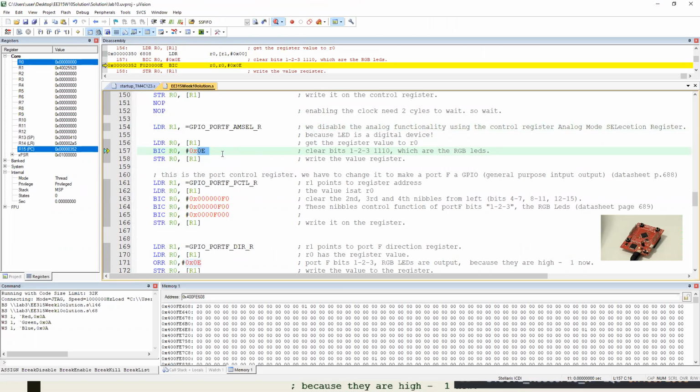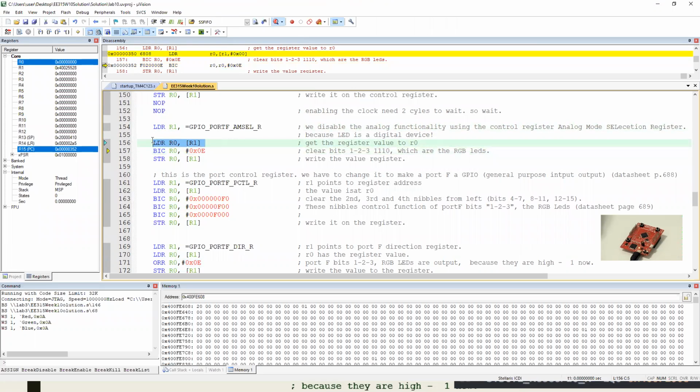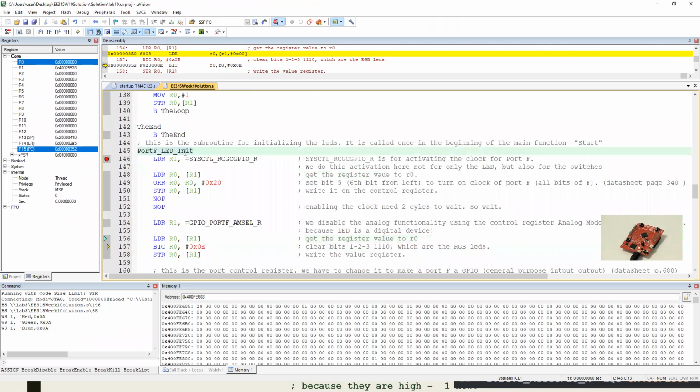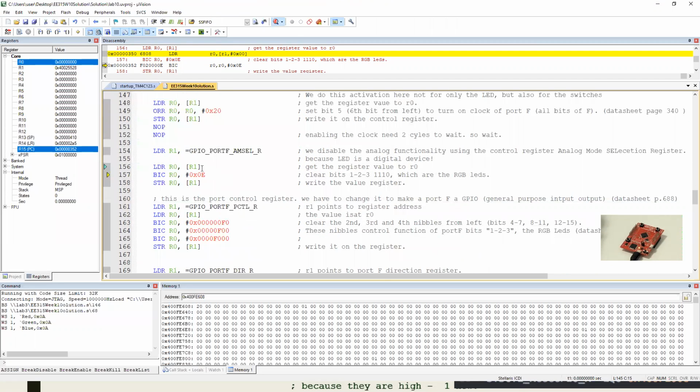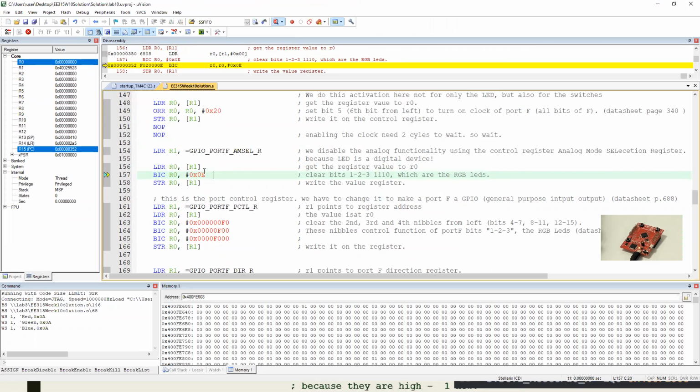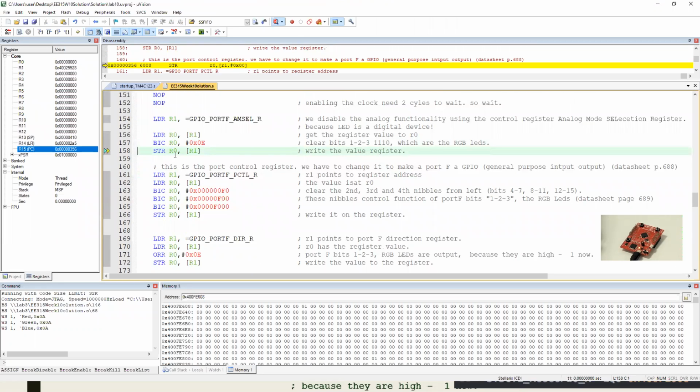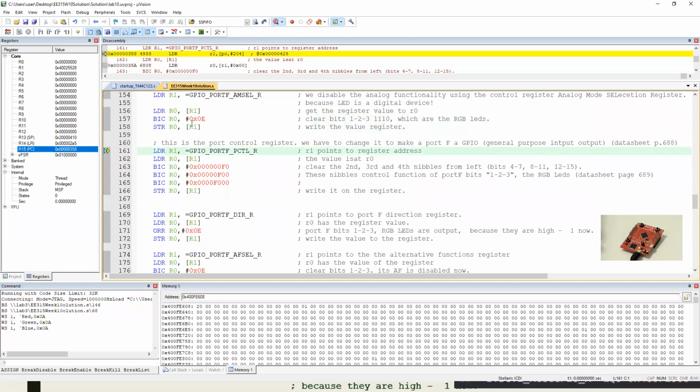So why am I doing this operation? Well, it is redundant, but I don't know if the initial value was this. When I reset it, it's 0, but maybe before calling this function, somebody else changed those registers and they were not 0. I don't know that. I know this because I'm debugging it. While you're running a big code, there is no guarantee that these are ones, these are zeros. So I clear R0's bits, it doesn't change, and write it back to R1, where R1 shows.